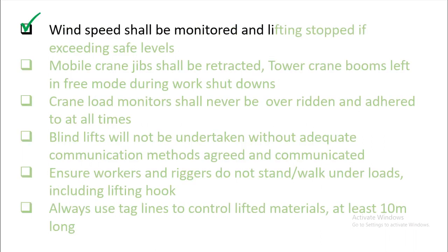Wind speed shall be monitored and lifting stopped if it exceeds safe levels. So when you are doing the lifting, as a lifting supervisor, you should always check the current wind speed at every location of your cranes.